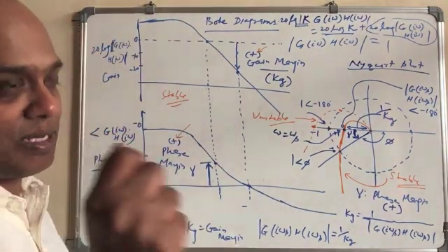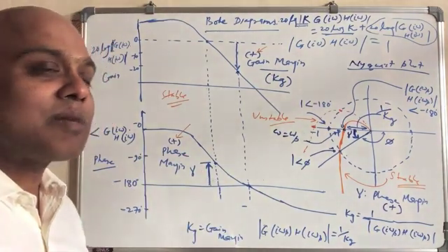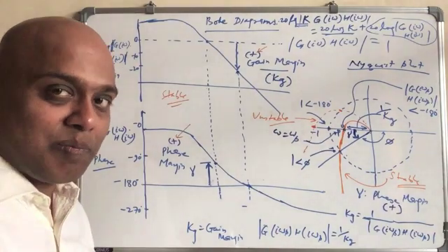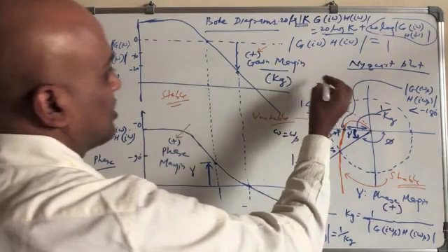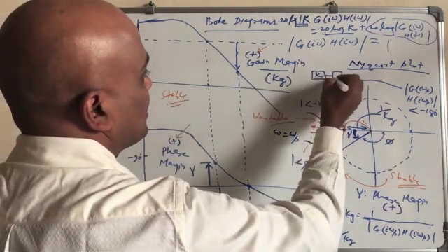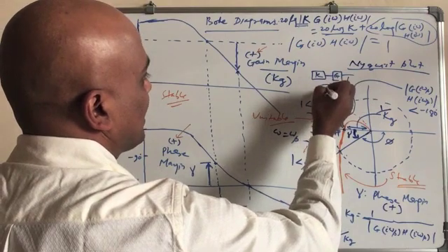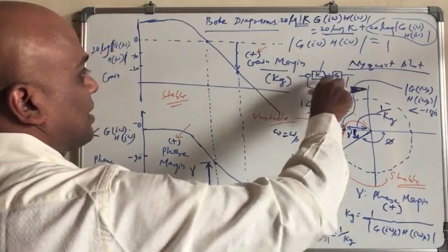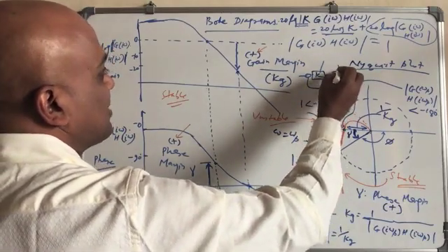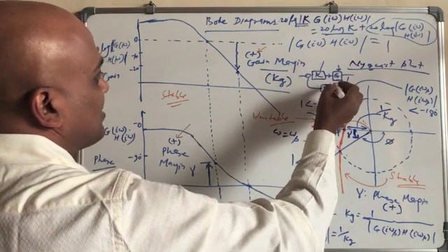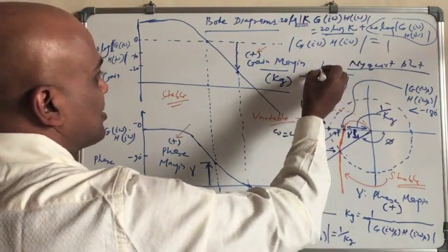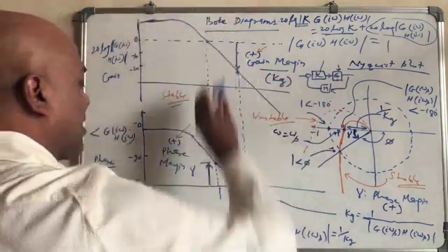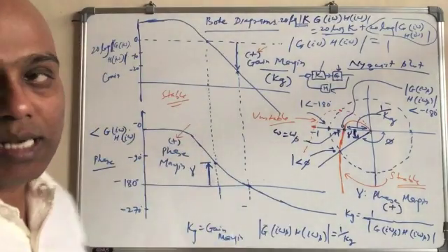Meaning that just a gain, maybe the proportional control. So you have k here, and then after that you have G, and then it goes to H like this, right? So if you know G, which you cannot change, or H, which you also cannot change, then you can introduce a proportional control, and we can change k in such a way that it goes up and down. Accordingly, you can have the required phase margin or gain margin.